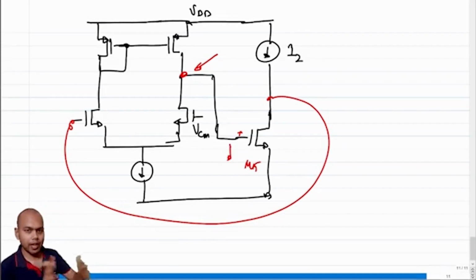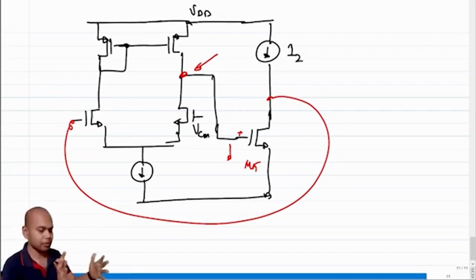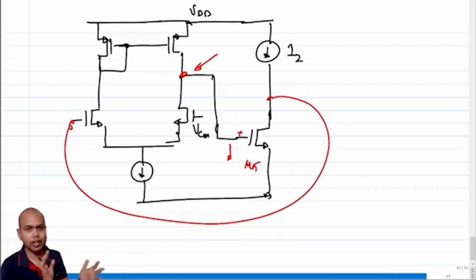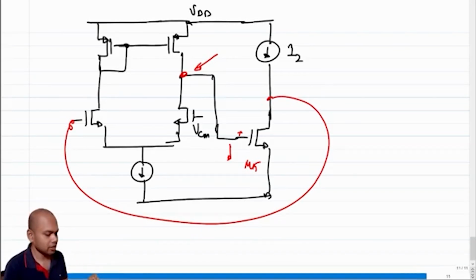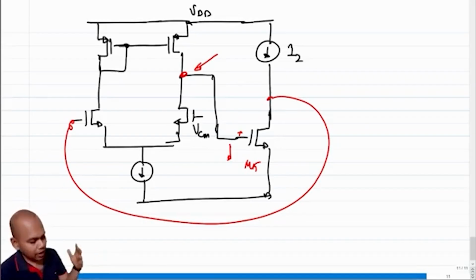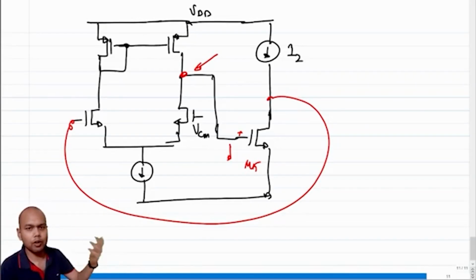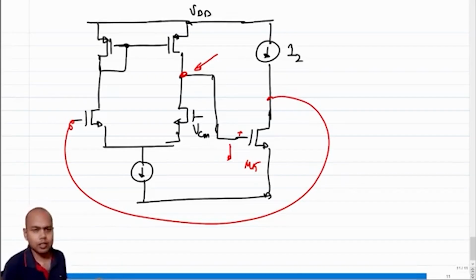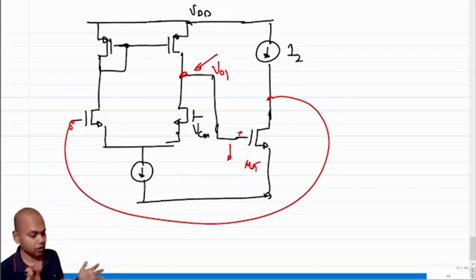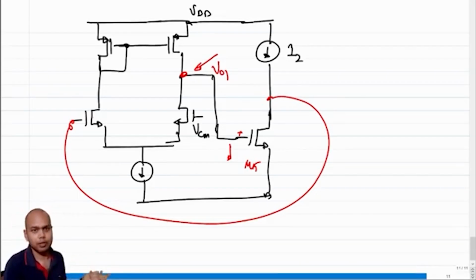So the overlap of the range of acceptable voltages might not be sufficient to use an NMOS second stage. But if VDD really comes down, let's say VDD is like 1 volt, then it's quite possible that the range of acceptable quiescent voltages of VO1 and the range of acceptable quiescent voltages for M5 VGS might be okay. In that case, an NMOS M5 is also probably fine.